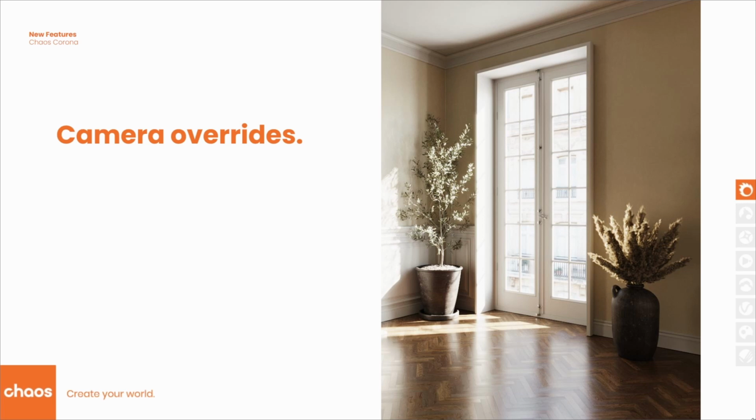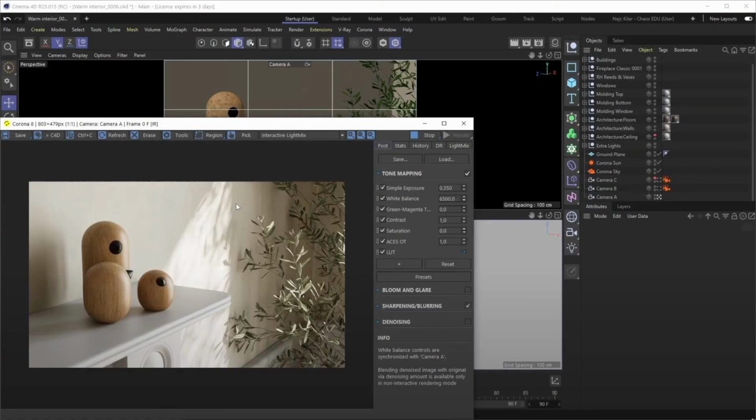Then let's talk about camera overrides, because these are really important in the new system. Let's just jump into Cinema 4D here. As you see, we already have a scene being rendered here. If you take a closer look at the camera that we're currently using, we're using the default Cinema 4D camera. It has no Corona camera tag applied to it, so it's not a Corona camera by any means.